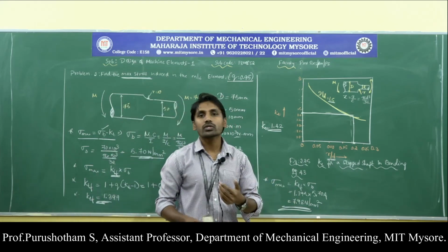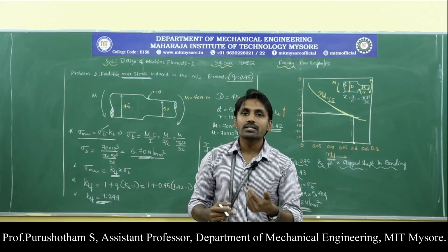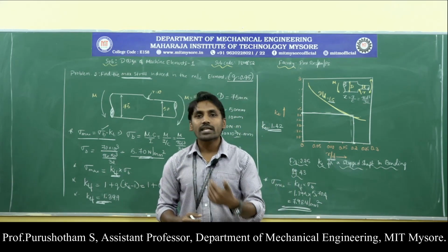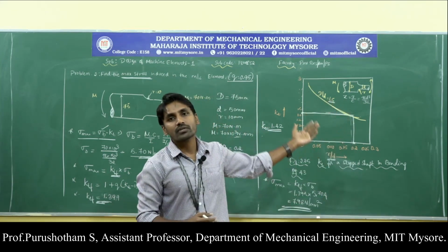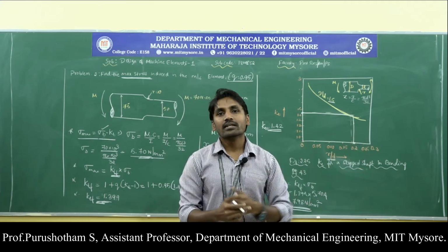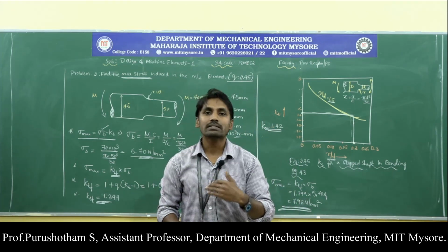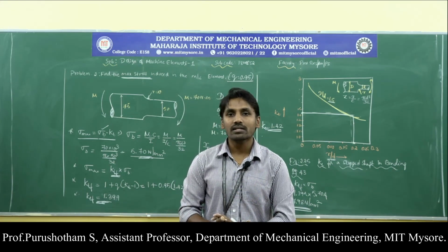So like this we are going to solve the discontinuities, maybe grooves, notches or fillets. For this type of problems also we need to refer to the figures in the data handbook that match the exact case. Then from that we can find out the stress concentration factor as well as the maximum stress induced in the machine member.